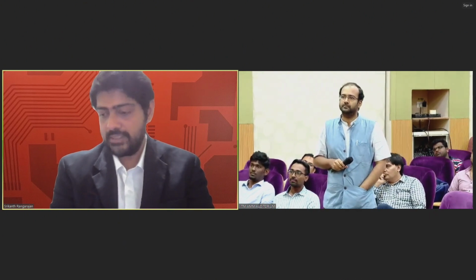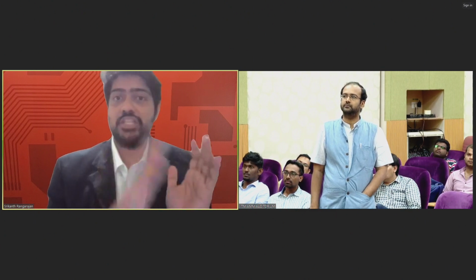Absolutely, Professor. Thank you really for raising this question because, as I was mentioning on the evolution chart, there's a seminal work by Tuckerman and Pease which is still sitting on paper. It has never been commercialized, though they were able to demonstrate that etching channels on the backside of a silicon can be very attractive, close to 790 watts per centimeter square. But the industries have always resisted such a change because no industry wants to touch silicon and have us routing the cooling through that. But what the industry also understands is that we are reaching the limits in every decade.